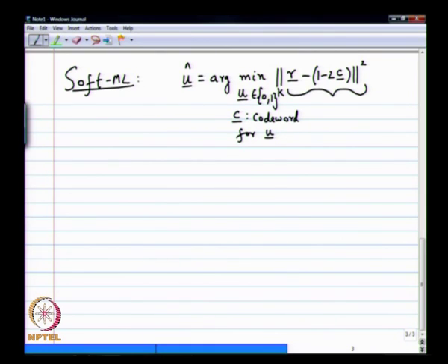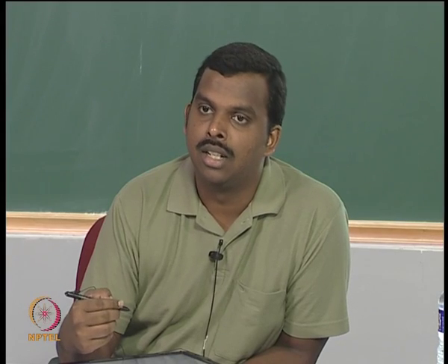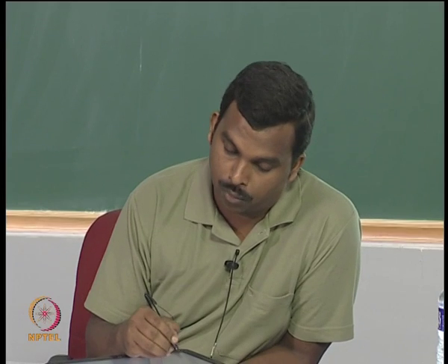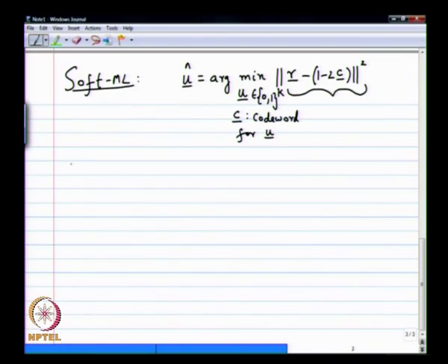It turns out because of the trellis you can do it sequentially as opposed to in total. So this task of doing the minimization can be done sequentially. That is the idea in the decoder. The efficient implementation of soft ML decoder for convolutional codes is called the Viterbi algorithm, after the person who discovered it, or well, the person who came up with it first. And we will describe that next.